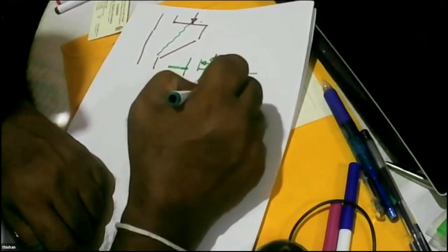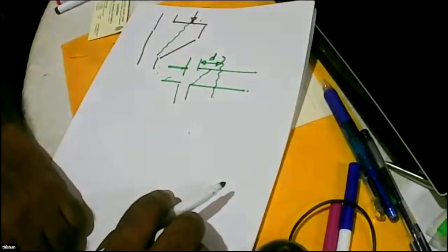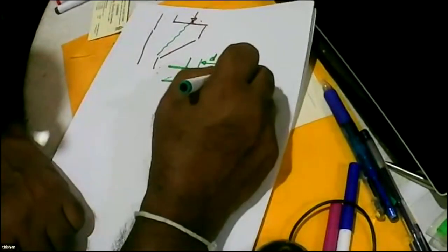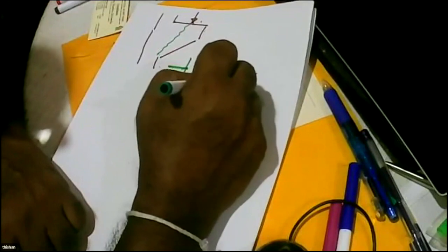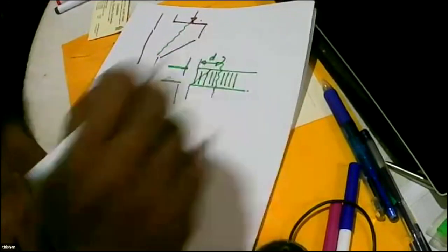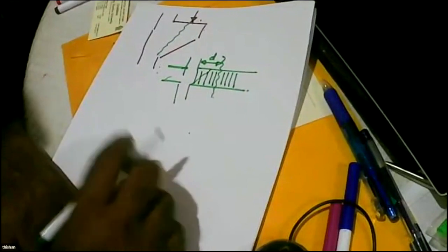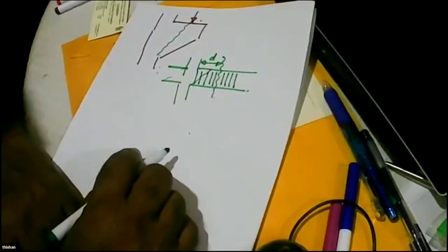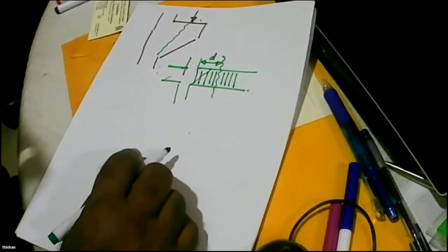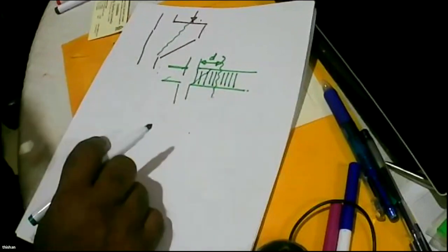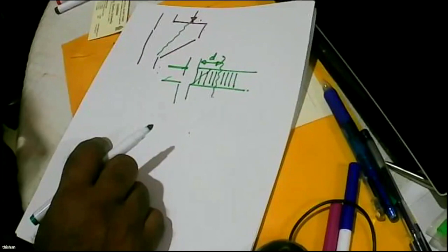Check the shear D away from the face of the support. Whatever the links that you get here, provide the same links up to the support. Is that clear, Bandhuka? Yes, sir, yes. Because of the enhancement, we are checking D away. Only because of this enhancement, because very close to the support, you can't get shear failures. Got it? Yes, got it.